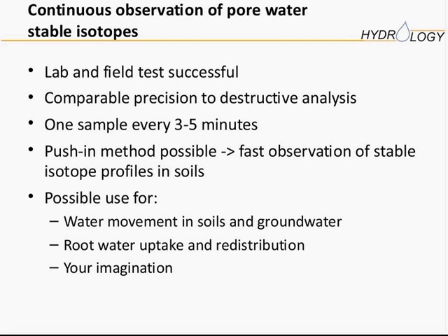Good. To summarize this part, the lab and the field test were very successful. We got comparable precision compared to the destructive analysis of soil water vapor. You can sample roughly 1 sample every 3 to 5 minutes. That's just the time it takes for the flushing, and then until the water vapor arrives at the laser spectrometer. This push-in method is possible.